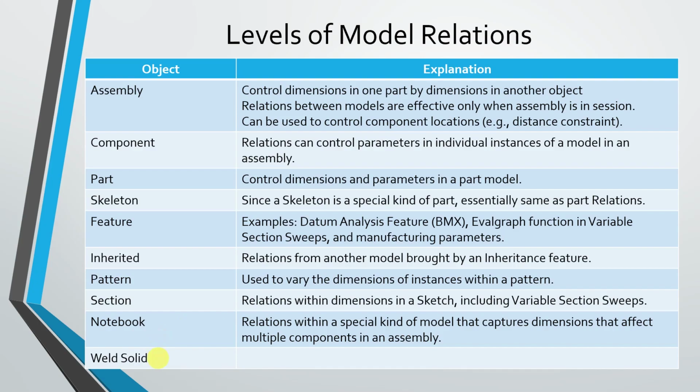And another level at which you can create relations in the model, weld solids. And to be honest, I have only touched the weld module a handful of times. I've never created a relation between weld solids that you can generate. And it was only a few versions ago in Creo Parametric that you gained the ability to generate weld features as solid features versus the non-solid surfaces that were previously generated.